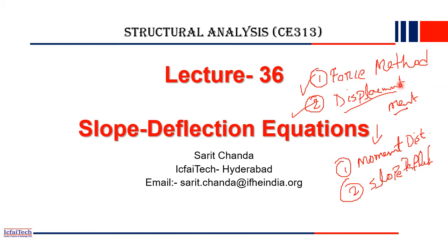Now in displacement methods, basically our unknowns are primarily displacements of a structure. We consider that as an unknown and then we derive our equations to solve the indeterminate structures. So in the displacement based method, there are two subtypes. One is moment distribution method, another is slope deflection. So in the last class, we have seen how we can use moment distribution method, simply distributing the unbalanced moment into the nearest supports, to easily analyze the indeterminate structure. So today we will see how we can use slope deflection equations to solve the indeterminate structures.